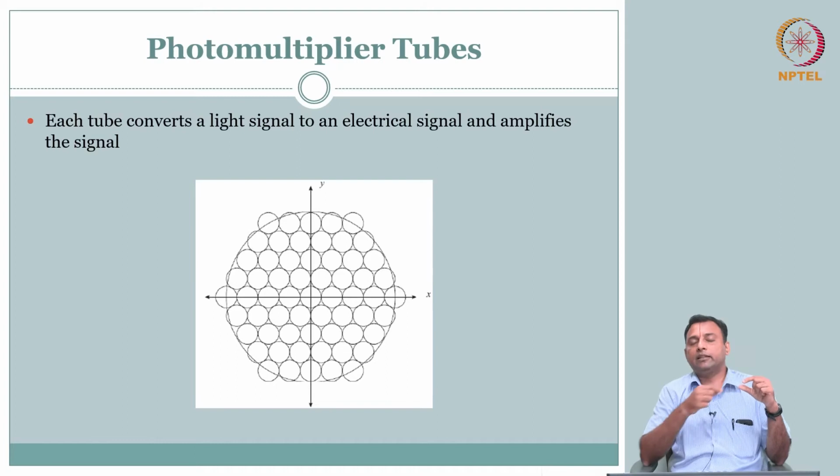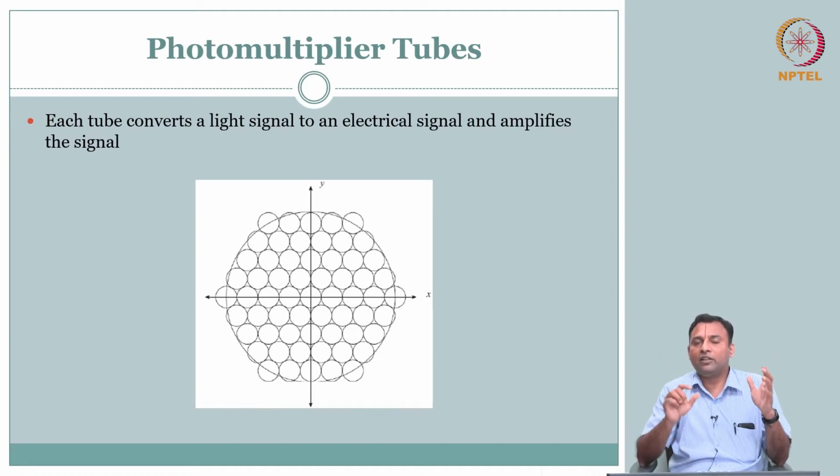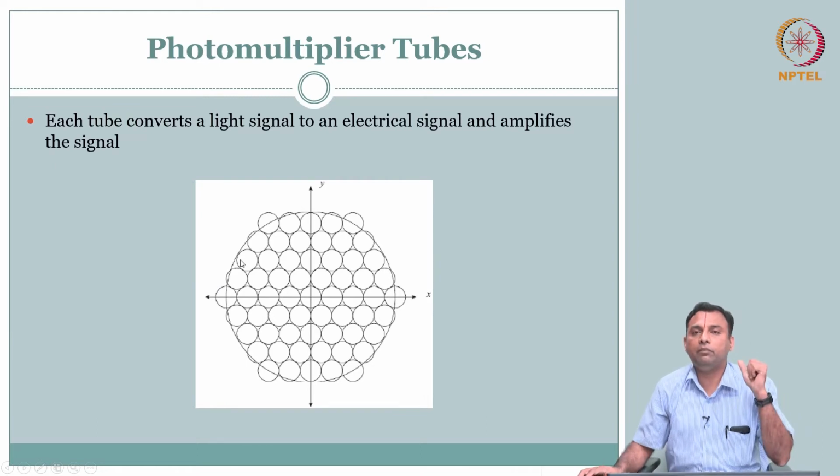Out of the scintillation crystal you get light photons, some number depending on the conversion. But then we need two things worked out. One is that I need to be able to amplify the signal, and the other is the XY plane. So this circle is, for example, your detector crystal, and out of the crystal are going to come your light photons.